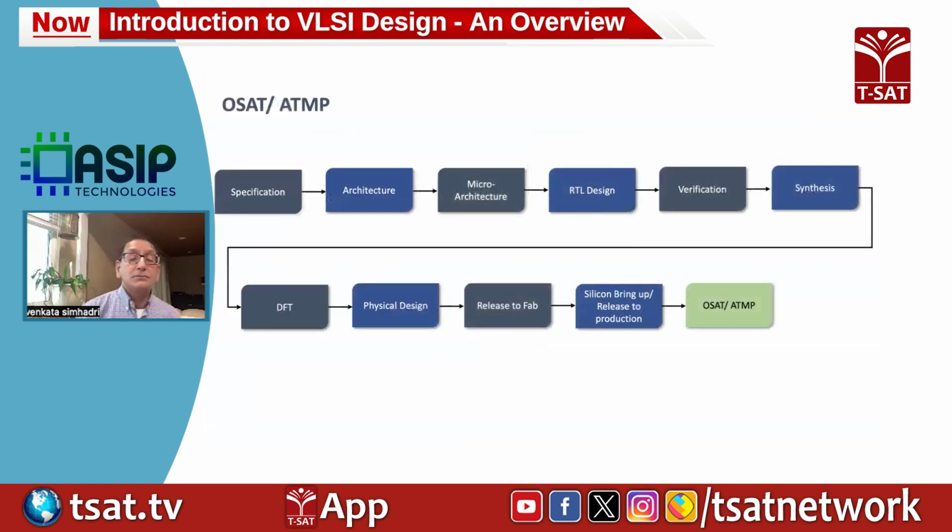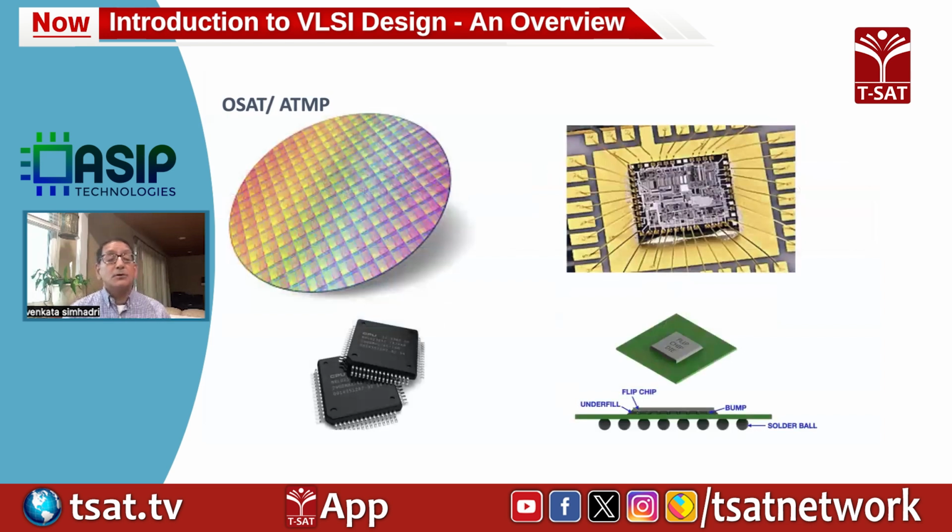And I will also talk a little bit about OSATs, or ATMP, you call it. OSAT stands for Outsourced Semiconductor Assembly and Test, because India is investing heavily in these things now, with the latest semiconductor policy from the central government. Once you fab the chip, it comes in wafer form. It's a big round 12-inch wafer, and each wafer may have thousands of chips.